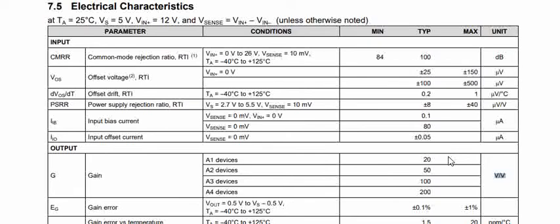When we say test bench level, basically they do it at room temperature, and some of the data sheets also mention the figures, the diagrams of how they have done it, what is the input voltage they have provided, what is the kind of voltage that they have tested with. So along with those figures, if you see the electrical specifications, you see here at 25 degrees centigrade, supply voltage of 5 volts, input of 12 volts, and we sense again. This is clear, right?